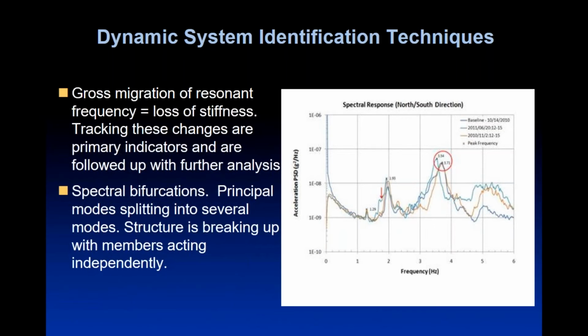On the more complex mode of vibration, we've got an increase in the frequency. So in the first mode, we've got a decrease. In the second mode, we've got an increase. Why? Because in the first mode of vibration, we had damage in a facade on this building. The second mode of vibration, they'd actually built new foundations to the structure. They'd strengthened it up. So they made the foundation stiffer, and this more complex mode, which has more influence from the foundation, had increased in frequency.